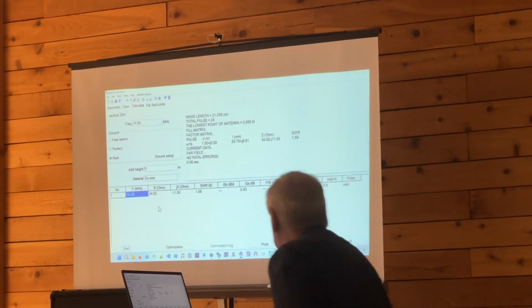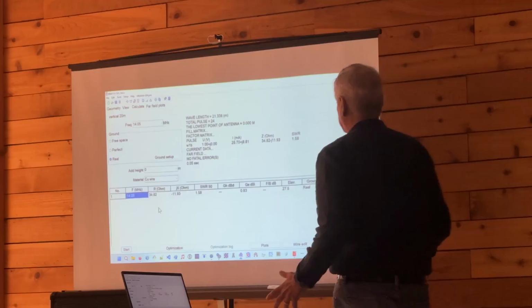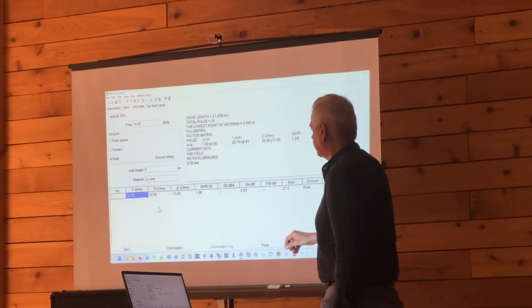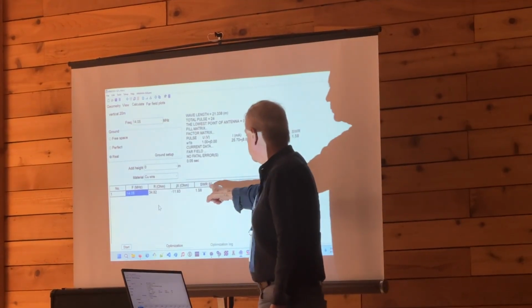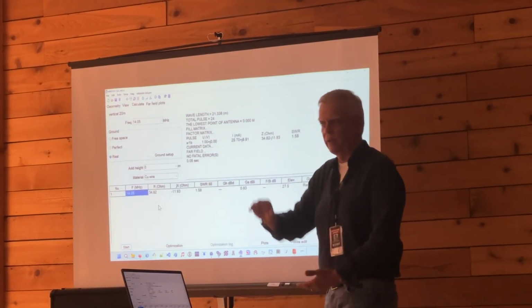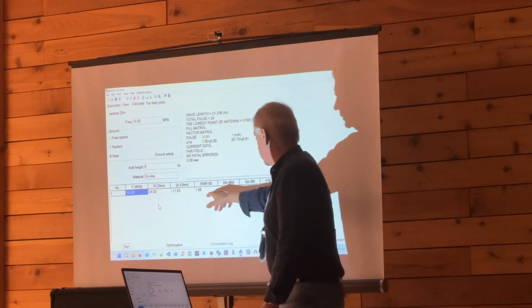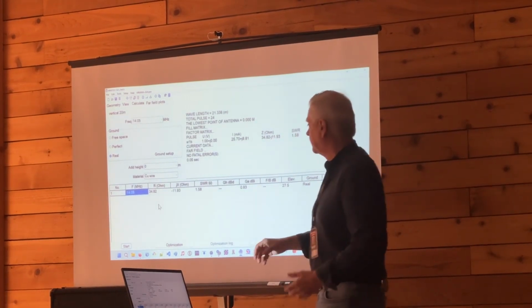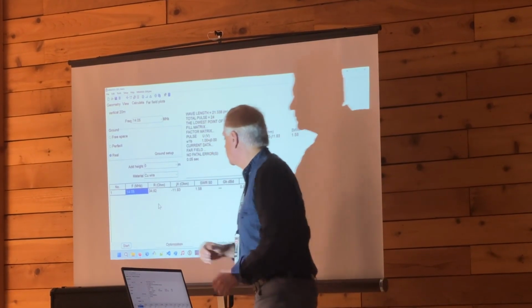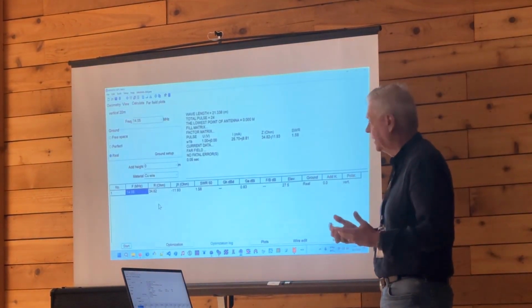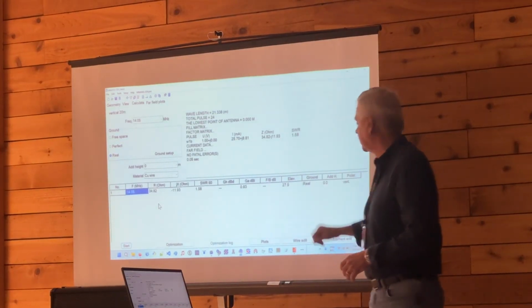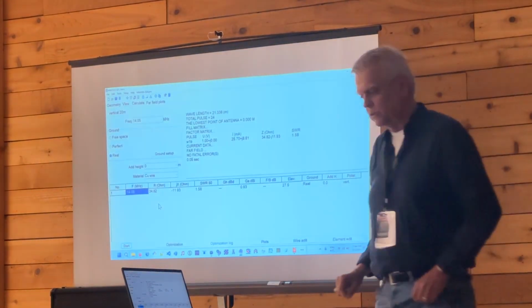What are we getting now from the program? We're being told a lot of important information that's just come up on this line. One of them is the SWR of the geometry you gave us, 5.1 meters, which is going to be 1.58, which is not bad. Our input resistance is 34.82 ohms. Again, not bad. Gain and all these kinds of things we'll delve into shortly.